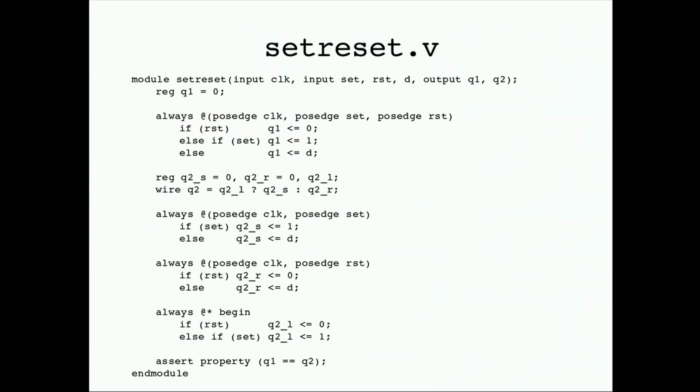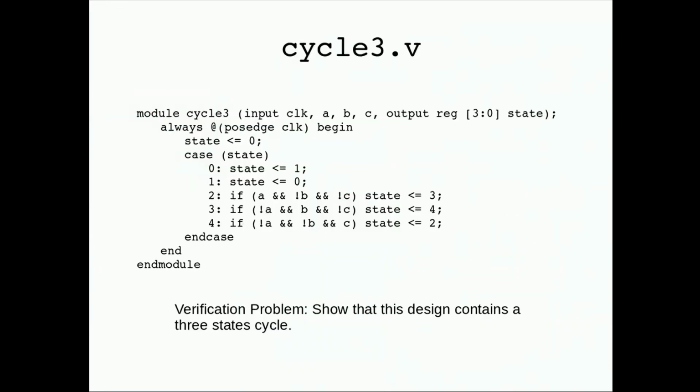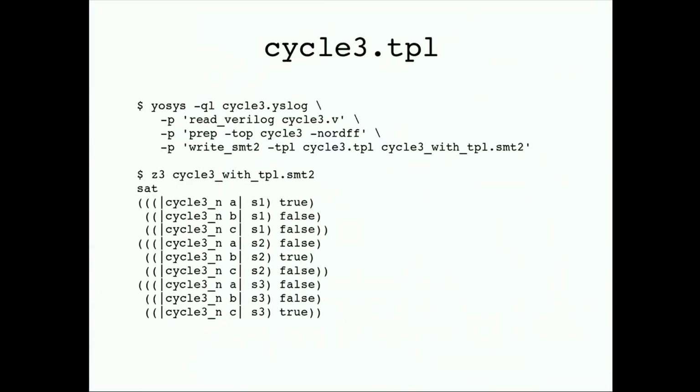Similarly, this is another design where I have a set-reset flip-flop. Never use something like that in a real design. It's horrible. But if you have to use it for some reason, we can actually check it here. And of course, this is actually what the Xilinx tools do for a set-reset flip-flop, because they don't have it as a hardware resource. They create this weird thing with 2 flip-flops and the latch and the mux. And we can actually prove that this is the right thing to do, that this still is a flip-flop like this. You can also do custom things. I'm not going to talk about them.